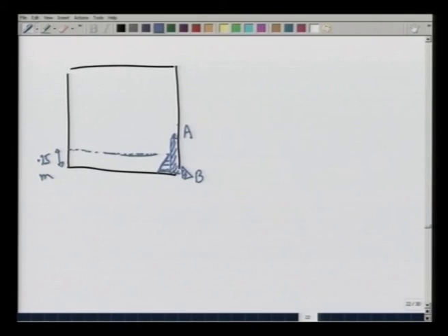So, in this lecture we have used the concept of centroid and the area and the first moment of the area of load versus distance curves to get some formulae to see where effectively a given force or distributed force acts, and then applied it in situations where a beam was loaded or when a sheet was submerged in water.